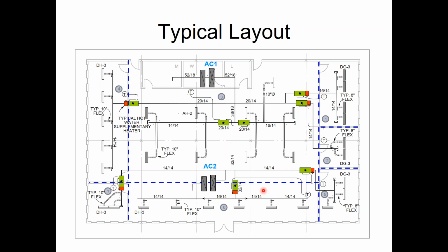Now, in the perfect world, I would have 1 rooftop unit for the west exposure, another one for the east, another one for the south, and 1 for the core. And then if there was no side building here, I'd have 1 for the north side as well. I'd have 5 rooftops on here. No one's going to pay to do that. So this is already a compromise decision here.